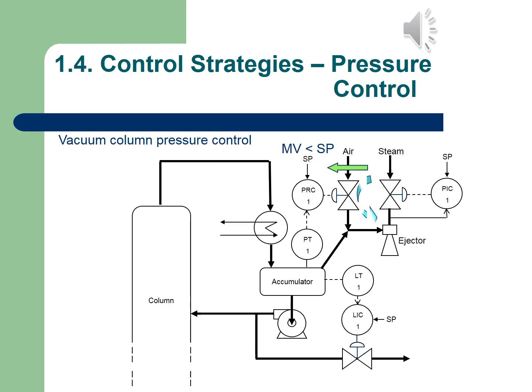Okay, so the next strategy is a vacuum column pressure control. I think what's important here is why vacuum. It just means that you will change the boiling points. So with a lower boiling point, less temperature will be needed. If you think about the example of boiling water in Gauteng and boiling water on Mount Everest, by having a lower surface pressure on the bottom product, it means that vapor can easily start to form at a lower temperature because of a lower boiling point.